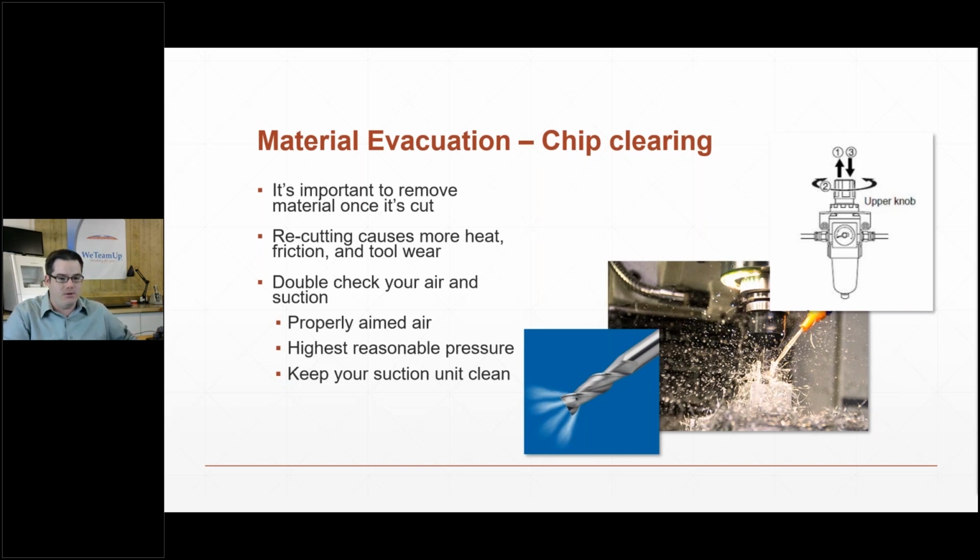So that debris, you want to get out of that area as quick as possible, because otherwise the tool will actually recut that material, which is not doing any work for you at this point. It's just waste, and it creates another abrasion point in another area for you to get a heat buildup at the tool's tip. So definitely make sure your air is properly aimed.